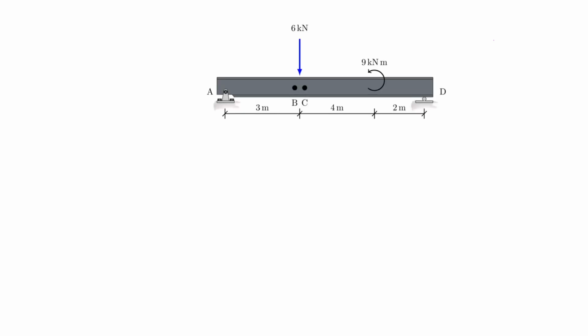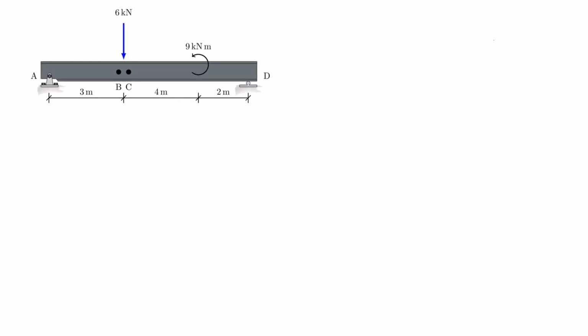So let's bring in this picture and find the internal forces to the right of this moment. You can determine them to the left of this moment yourself, but for speed reasons I'm just going to look at that location. To do that, I'm drawing my free body diagram of that portion. This will also give us an opportunity to use the left cut.